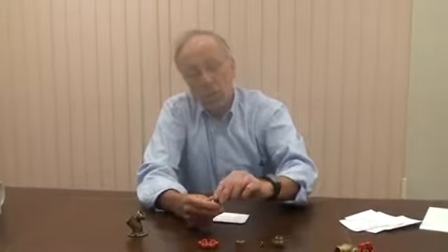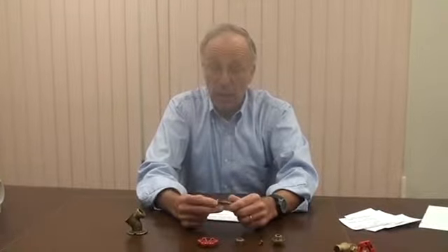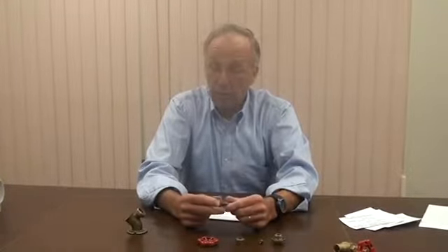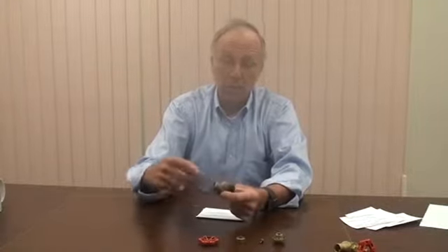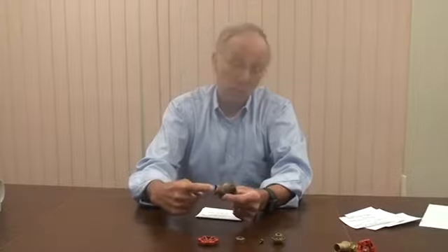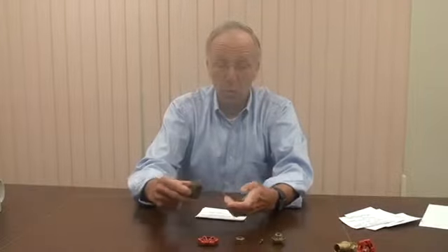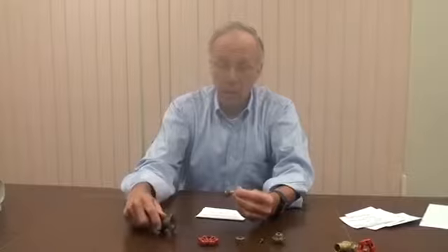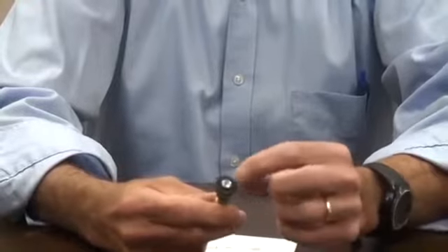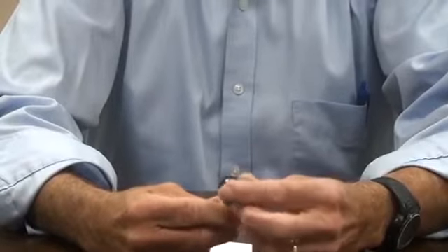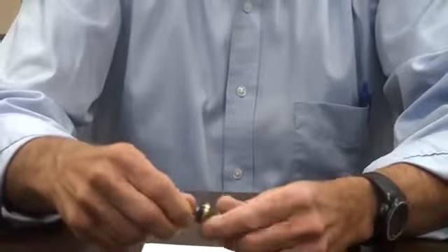Now we look at what causes the valve to actually seal off the flow from the indoor plumbing out toward the hose connection. So what we have here is the valve stem, which really can be disassembled into three pieces. At the bottom of the valve stem is a rubber washer that's removable, and actually if this washer wears out it can be easily replaced, and it's held in place by a screw.